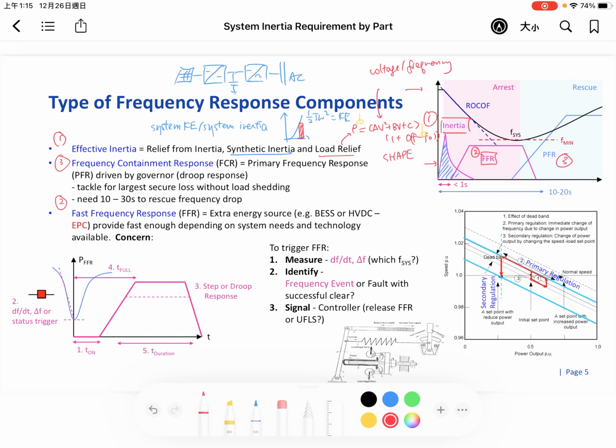There is a capacitor here, the DC link capacitor, and once there is some kind of emergency, just like a power discrepancy, we try to remove the charge to the grid first. The voltage will drop, but anyway, we try to restore it later from the PV. It also explains why we can provide more power during system emergency, but then we will have a power drop because we need to restore it from the PV.